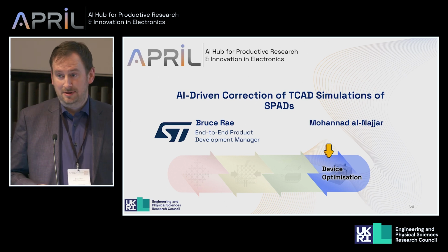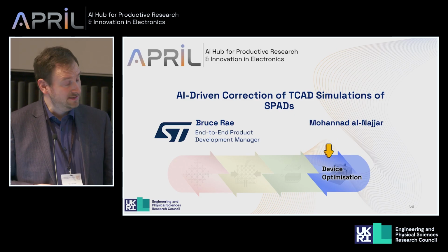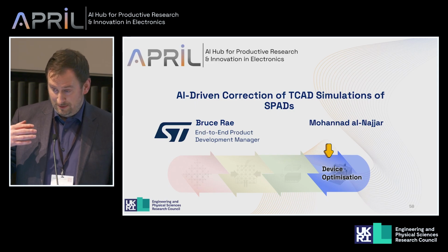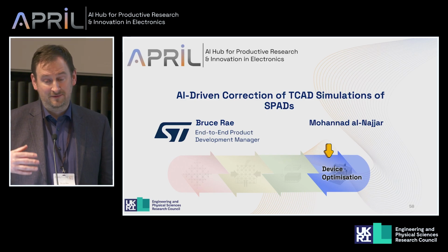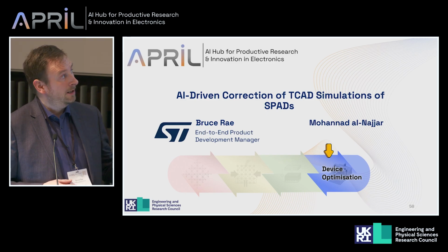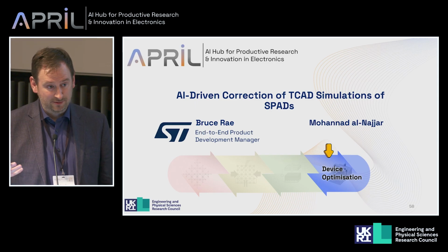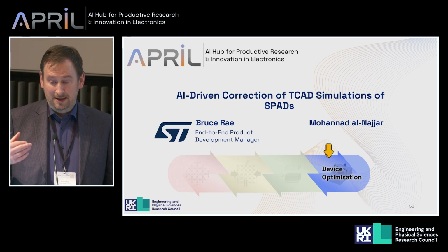So it's essential to have accurate TCAD in order to predict the behavior of these devices. In addition to that, we're an industry player, and we're trying to implement these in very expensive advanced CMOS technology nodes. Our latest SPADs are implemented in 3D wafer stacking technologies, and therefore it's an extremely expensive process.